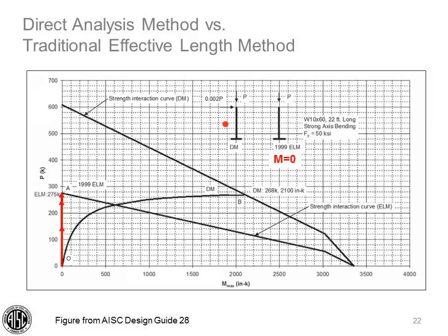In addition to the axial load P, we apply a notional lateral load of 0.002 P and reduce the column flexural stiffness. Now let's look at the axial load in the moment graph. We'll start by applying our load and track our analysis on the graph as the load progresses.